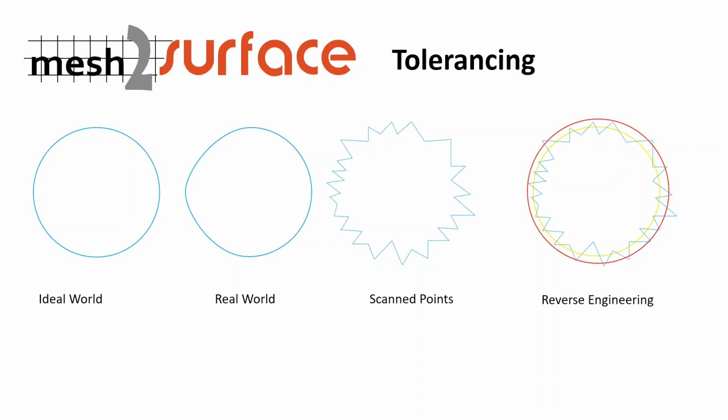But the reality is that up to today, for general mid-range scanners, we are talking about between 20 and 50 microns, which means that if we give this object to the designer and he needs to do reverse engineering, he needs to decide what actually is needed. Is it the yellow circle or is it actually the red one? Which one is the correct one? So there are many questions.